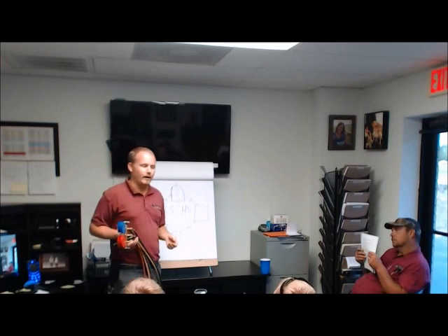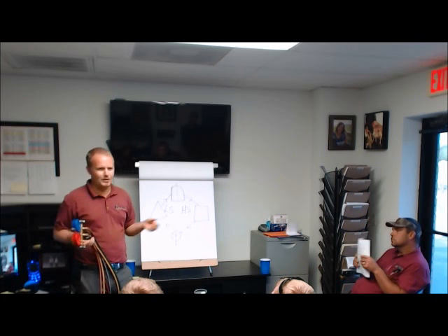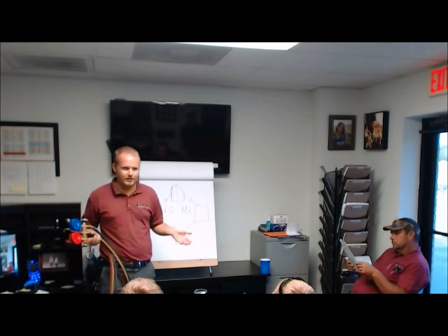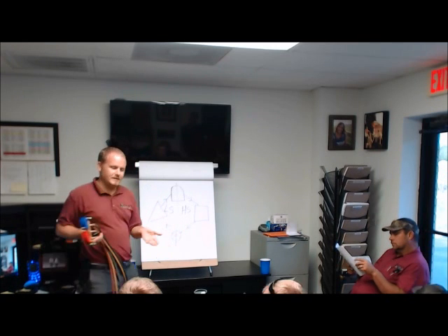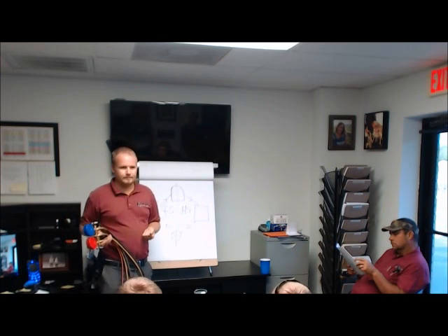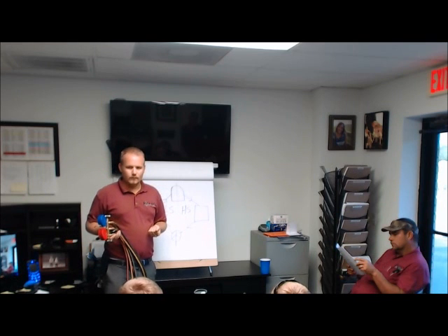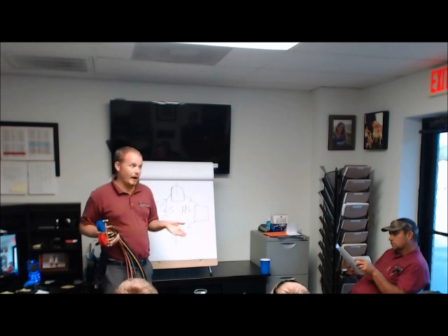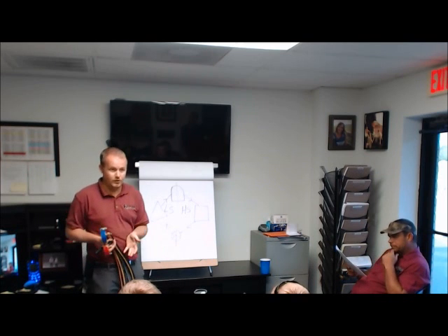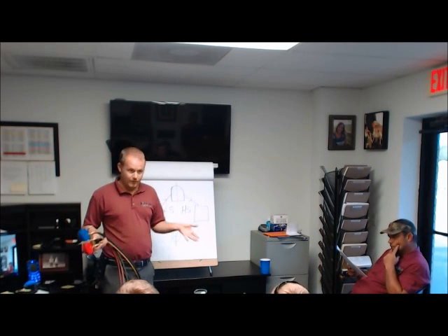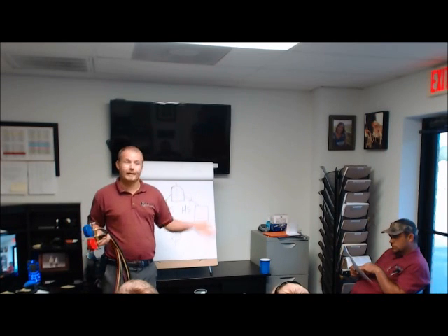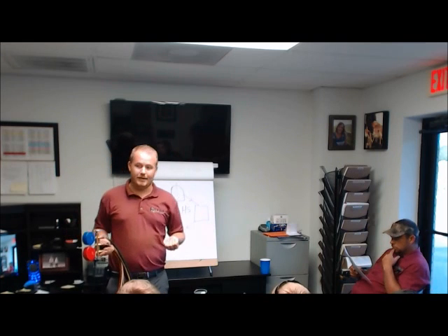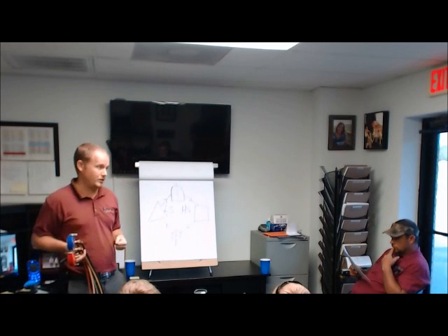That's like saying, well, how can I tell how hot this air is going to be based on the temperature around it or based on the pressure? Well, you can't know because it's not in saturation. This air isn't in the process of boiling. So I can't really tell you anything about what temperature it's going to be. There is no reference point. Correct. If it's in the process of boiling, it can't be much higher than saturation. So you have a window of reference. It can't be higher than saturation at all as long as you know what the pressure is and you know exactly what the matter is that you're dealing with. If you know what the pressure is and you know what the matter is and it's in the process of boiling, it will be this temperature. In the same way, saying water will be 212 at atmospheric pressure at sea level.